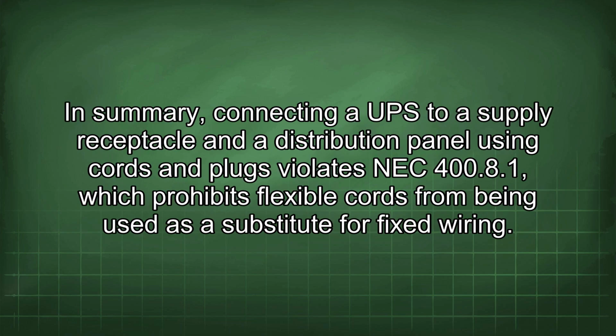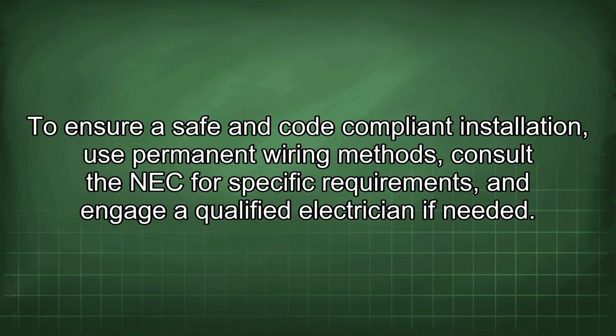In summary, connecting a UPS to a supply receptacle and a distribution panel using cords and plugs violates NEC 400.8, which prohibits flexible cords from being used as a substitute for fixed wiring. To ensure a safe and code-compliant installation, use permanent wiring methods, consult the NEC for specific requirements, and engage a qualified electrician if needed.